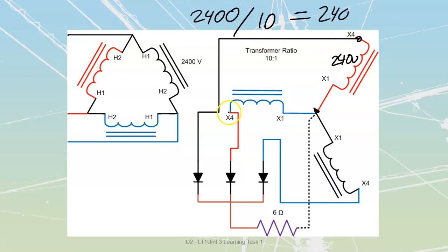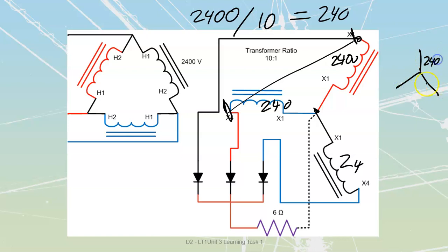which means that overall my line value for this is going to have to be higher, right? From here to here, because if this is 240 volts, then this is going to be 240, and this is going to be 240. We can draw it as being just off on the side here, 240, 240, 240. Our line-to-line value on a Y has to be root 3 times larger.